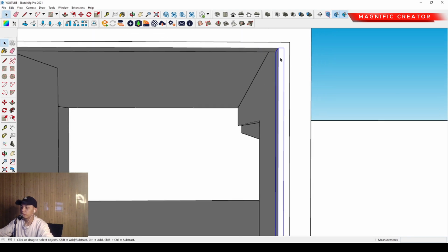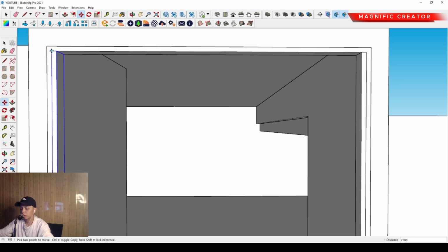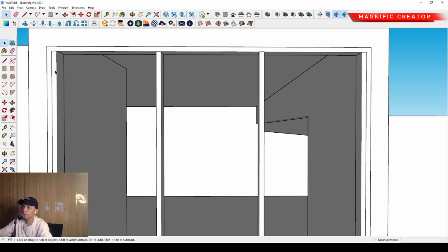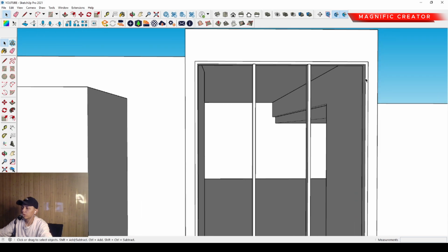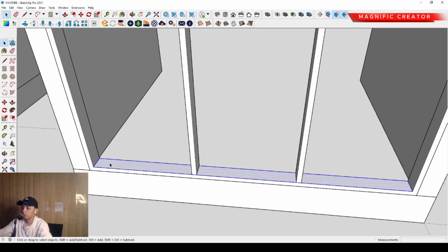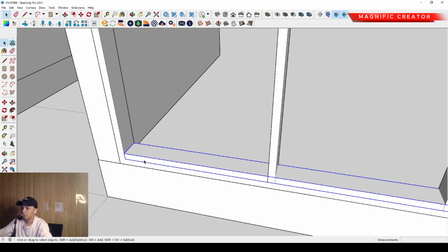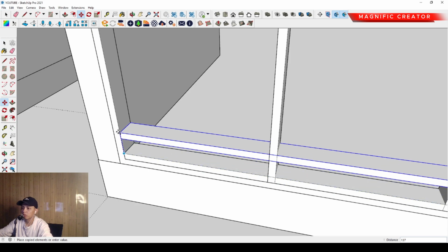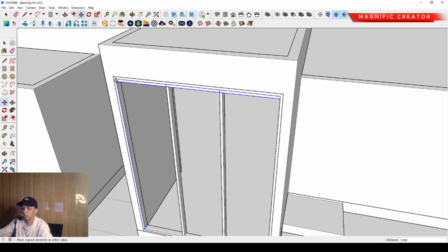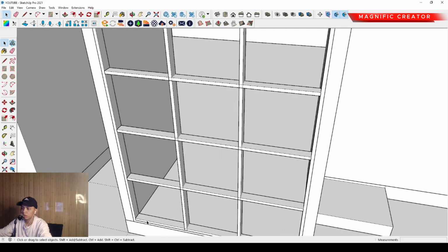Okay, so then we can move and duplicate it, press Ctrl, place on this position, and then we can type 3/ and enter. So then we can erase it. Then we have to make another frame. We can make the horizontal frame, then push it up around 40 millimeter. Then we have to make group, make component, and just create.